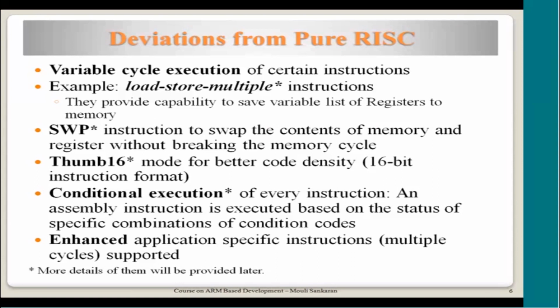One example is the load store multiple instruction, which helps you store multiple register contents into memory or recover multiple 32-bit values from the memory into registers. So a single instruction takes more cycles based on the number of registers in it.